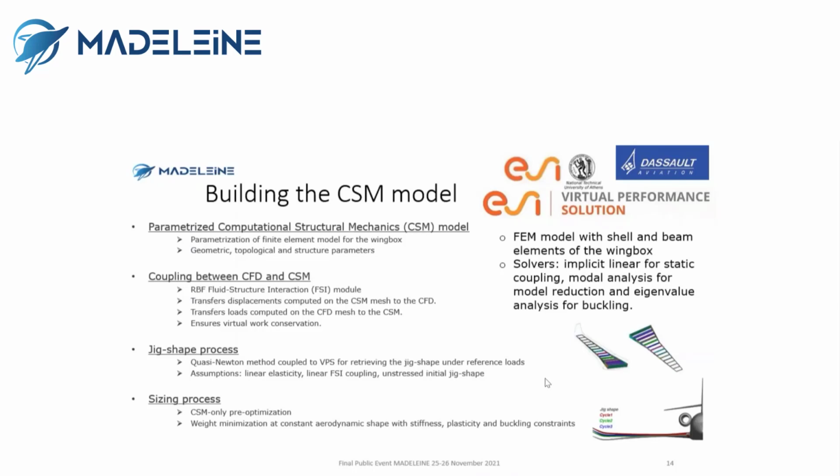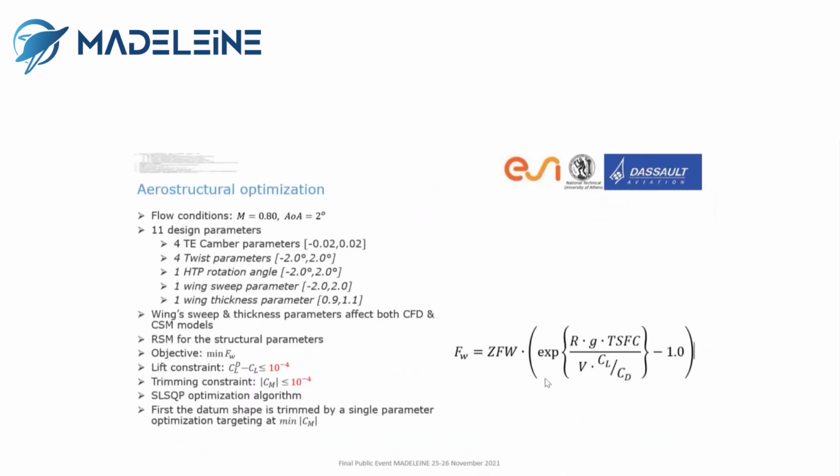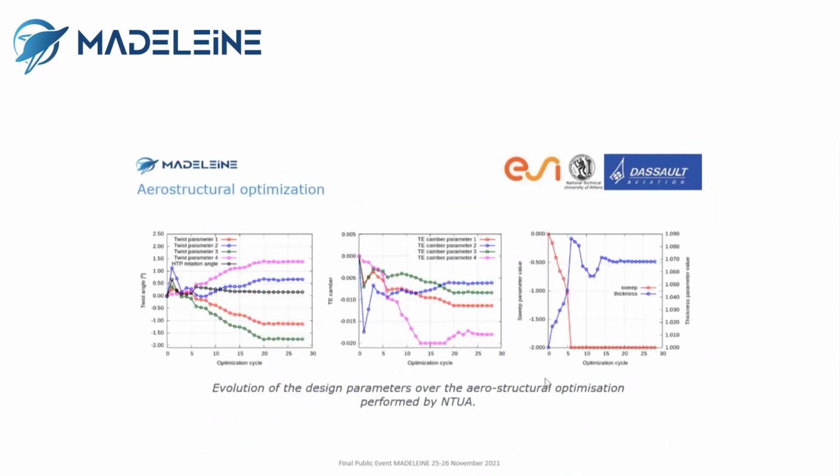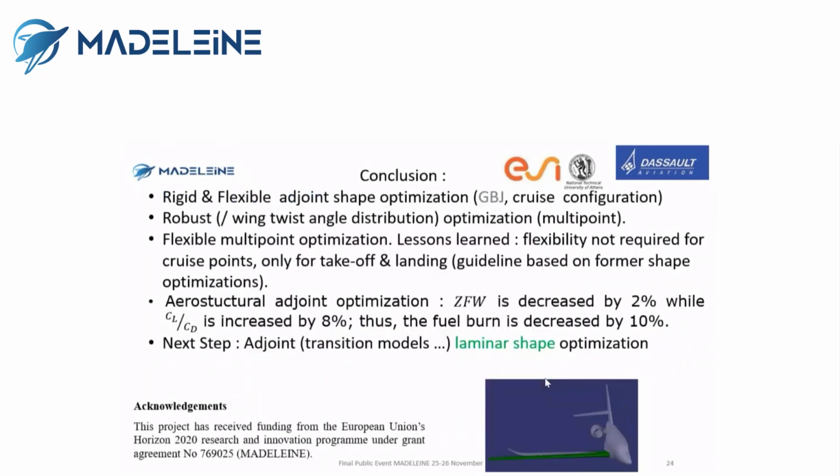And the last question, from Gilbert: you mentioned in your talk a remarkable 8% L/D improvement, rather large. Does that mean the starting wing should have been a better design in the first place? No, it's in fact a choice problem, and we have to take into account a lot of loads for CS 25 certification, and also takeoff and landing points for aerodynamics.